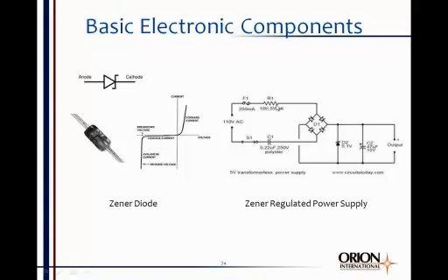That's your heat source. A lot of the rest of the voltage is going to drop right there. Okay. Then you go into this diode bridge. That's just a full wave bridge rectifier using standard diodes. Then we come back out to a capacitor. The capacitor doesn't really serve a major function in the explanation of this circuit.